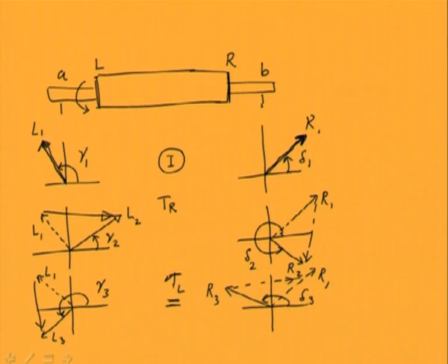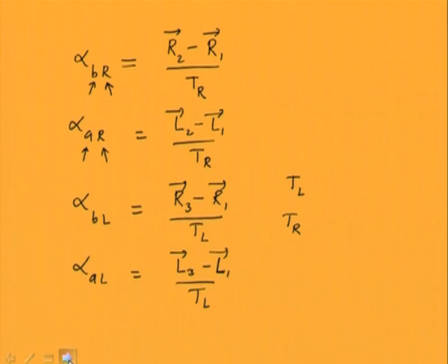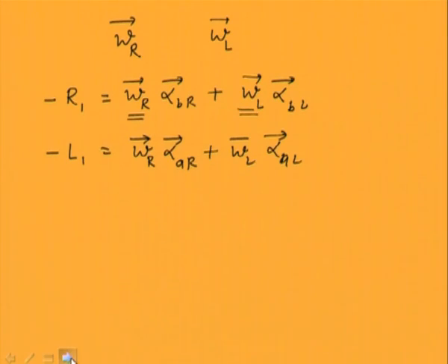That means there is no vibration of the rotor when we are having no trial mass. Okay. So with these correction masses we expect that the rotor is totally balanced, because of that we are getting these responses which are negative of the response without balancing.